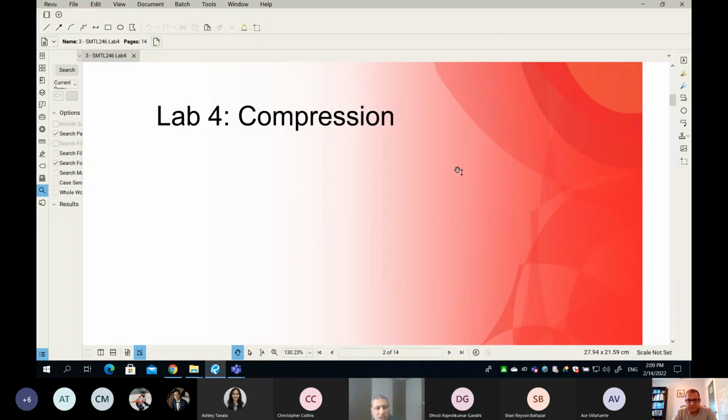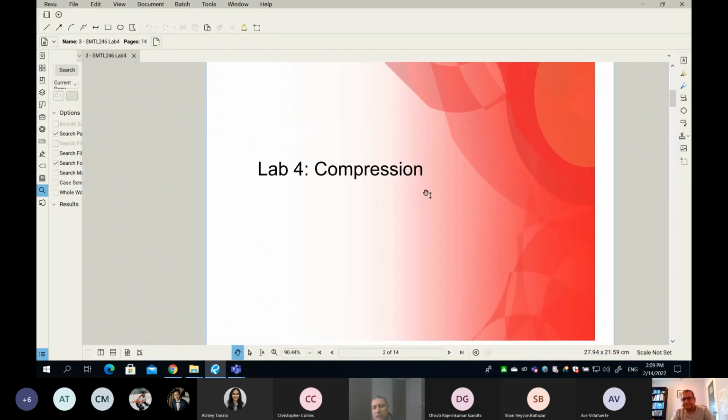All right, so today in our class, we have only one lab to cover, and you can see the name called compression. You will see the discussion today will be very, very similar to what we've done in the last lab. Remember, the last lab was about tension, and it means we're holding our specimen and we're trying to elongate the specimen. In today's class, we just have to reverse the force. So instead of applying tension, we simply compress our specimen, trying to make it shorter.